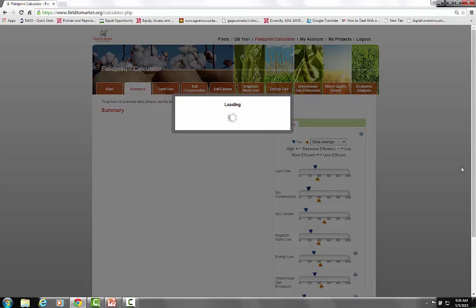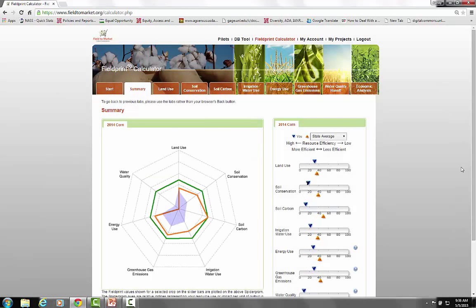Soil conservation will have water and wind erosion numbers associated with it. Over on the slider bar on the right-hand side, there's also a black T. That's your soil's tolerable loss as defined by the NRCS in tons per acre per year. So that T value, you certainly want a goal of being under T. T still permits a high level of crop productivity to be sustained economically and indefinitely over time. And farmers continue to improve and reduce soil erosion loss on their farm fields. And we would like to see this number under T if possible.